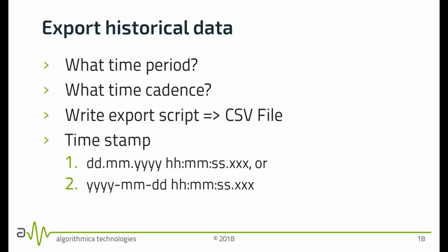So if we're optimizing a chemical process that takes place over the scale of many minutes, then it might be enough to sample the process every 5 minutes or every 1 minute. If we're looking at damages to machinery that might occur within the space of a few minutes, then we might have to sample that every 60 seconds or every 30 seconds. So that question is answered essentially by the process speed or the damage mechanism speed that we're looking at here.